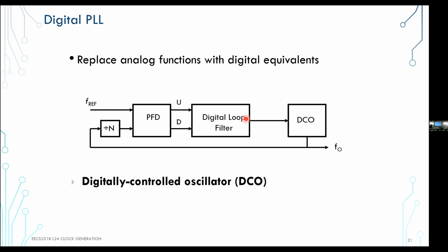It directly influences the VCO. So there's a noise from the regulating resistor. There's noise from the charge pump as well. Charge pump transistors have noise current. That noise current also integrates and passes through the loop. So you can do all these noise transfer functions. I just gave you a few that are kind of in digital PLLs most dominant because of the digital supply impacting the VCO. But in general, you have all these noise sources passing through with different noise transfer functions to the output. So you have to analyze them all.